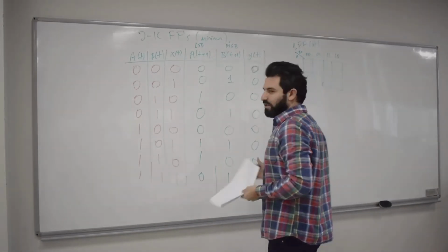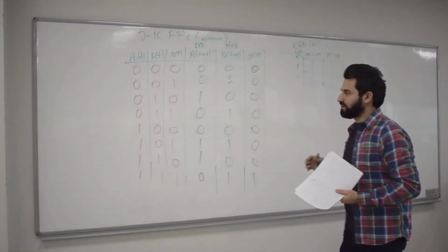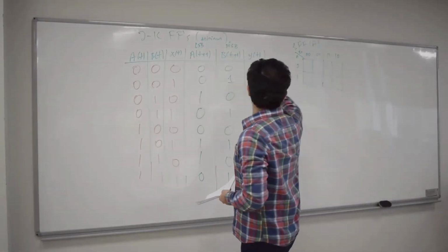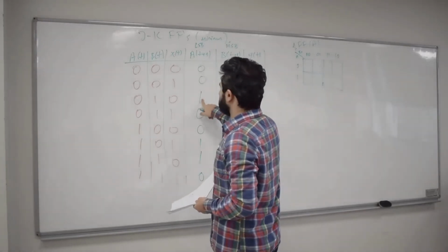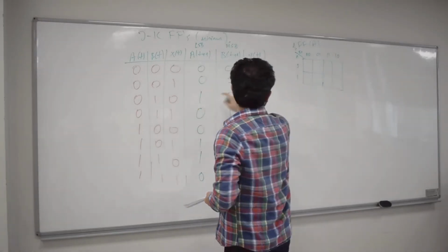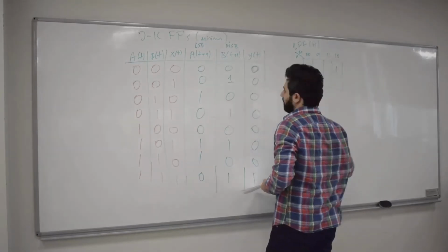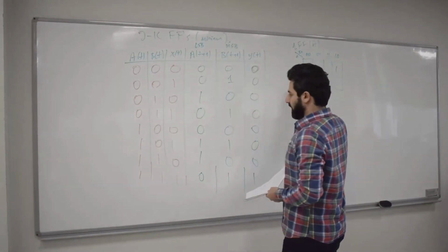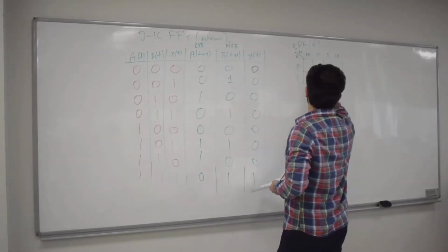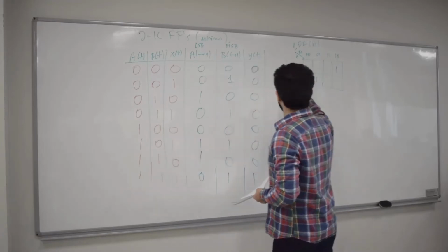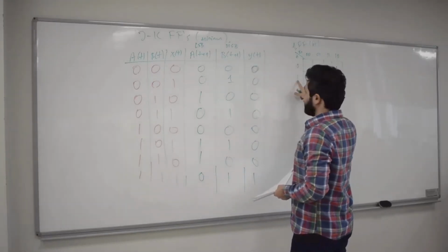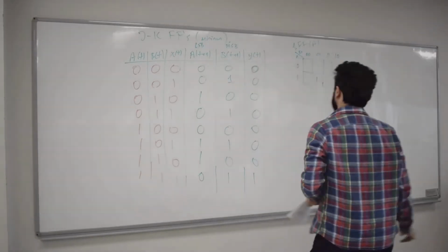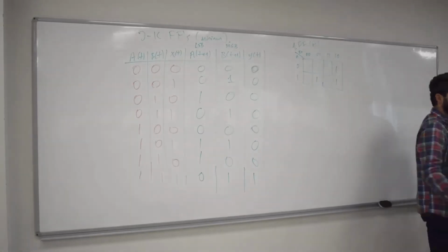From the Karnaugh map, we're going to be using Karnaugh maps, you know, a lot of times in our sequential circuit design. Okay, so when I see here, where are my ones? This is 1, 0. I've got 1, 0. So this is 0, 1, 0. I've got 1 here, and I've got 1 here, which is 1 and 0, 1, which is here. And I have got 1, A, B is 1, and X is 0. Okay? That's my 1, right? And that's it. There are three ones, as you can see.